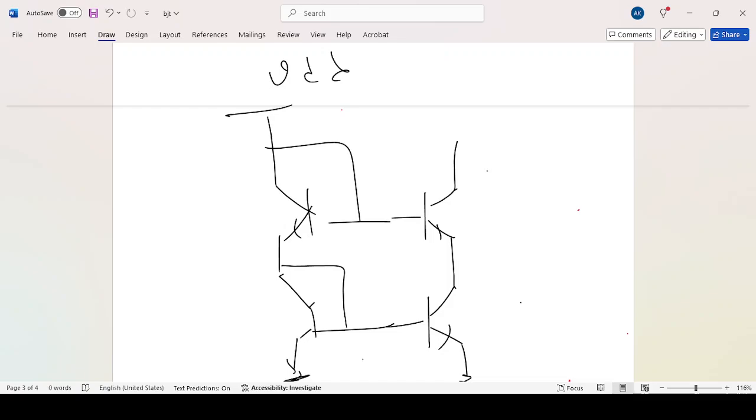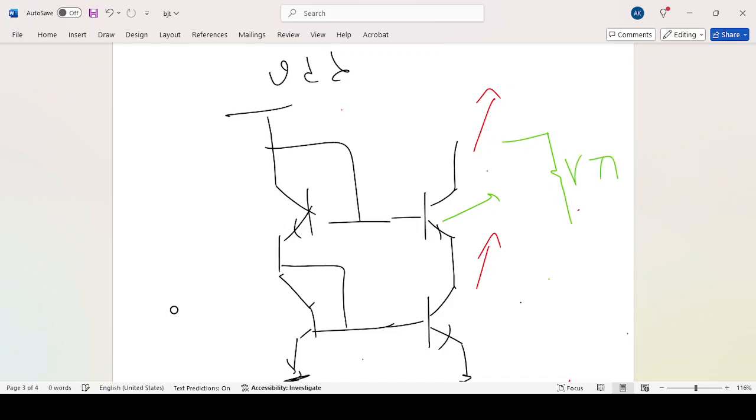I always like to do this. So when this is going up, it's a common base, but as it's BJT, not CMOS, we will have another path through V pi. Here it will be like a V pi, R pi, V pi, and the Rm, as I showed you, Rm of this guy and also Rm of this guy, and the R pi of this guy.